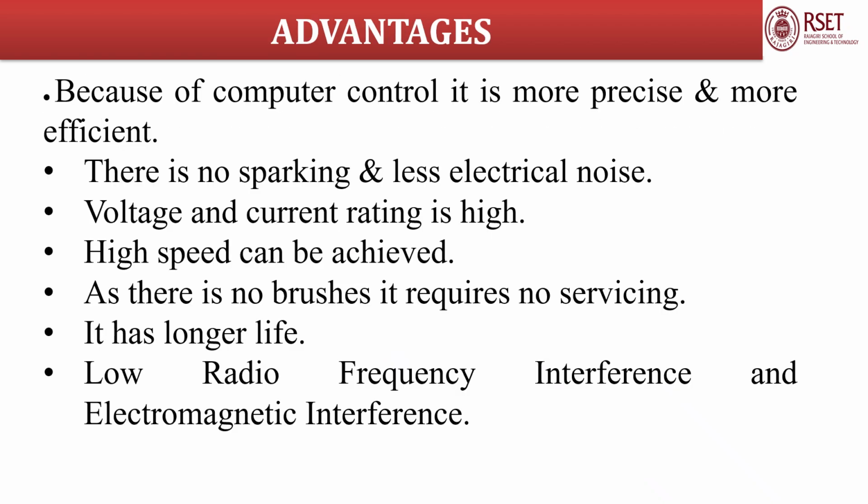Now we will see the advantages of the BLDC motor. BLDC motors offer several advantages. They provide high precision and efficiency due to the electronic control. There is no sparking, leading to reduced electrical noise. They can operate at high speed and have a longer life since brushes are absent. They also produce low frequency, radio frequency, and electromagnetic interference, making them ideal for robotic applications.